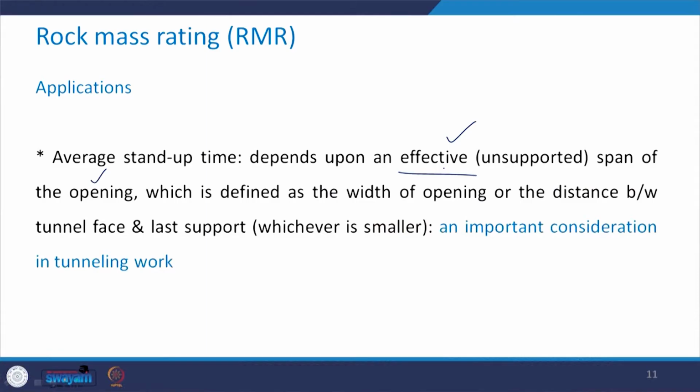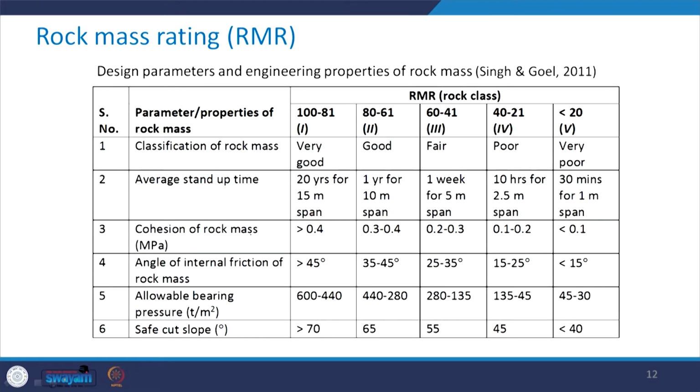So, the average stand up time depends upon the effective span of the opening. That effective span is defined as the width of the opening or the distance between the tunnel face and the last support, whichever is smaller, and this is an important consideration in tunneling work. Take a look at this table once again and focus on this row. This gives us the idea about the average stand up time.